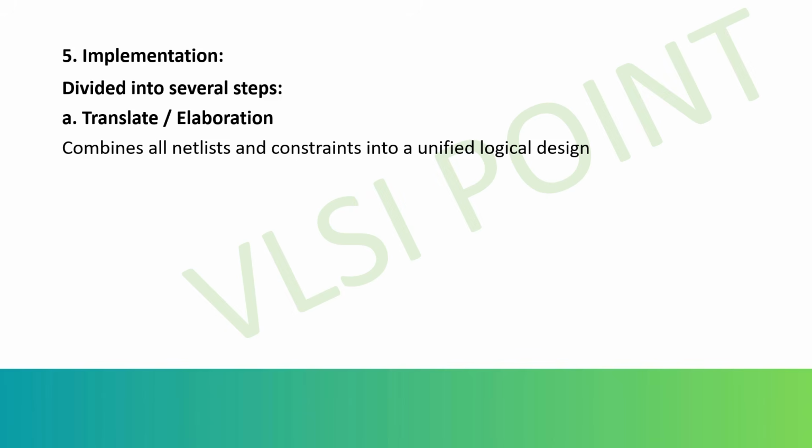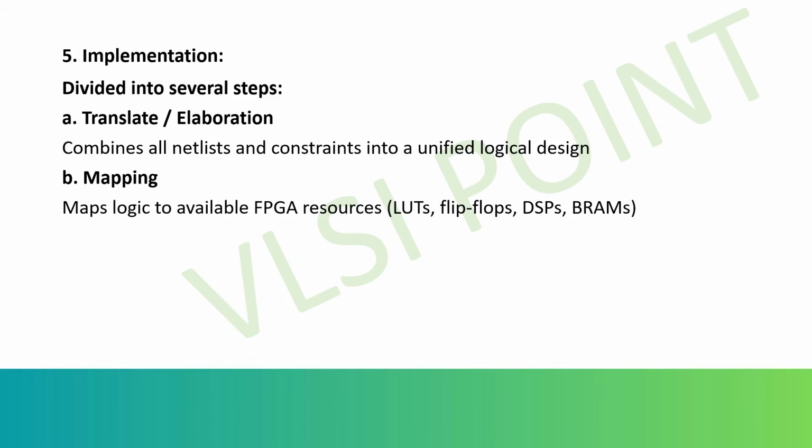Map means map logic to available FPGA elements. Mean to say, translate combines all the netlist and constraints into a unified logic design. And then there will be mapping. So it maps the logic available to FPGA resources like LUTs, flip-flops, BRAMs, or DSPs.